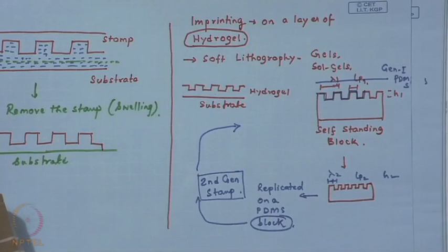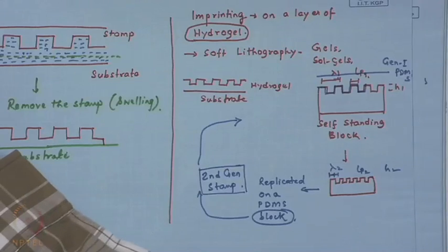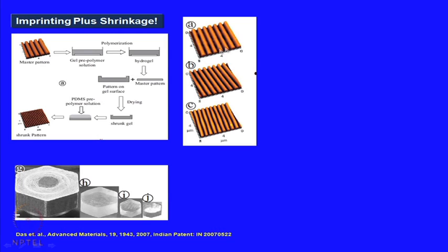So, you see here that starting off with a layer which is, let us say, a periodicity of 1.5 micron, in the second generation you achieve roughly 40% shrinkage. So, the periodicity has now dropped to about a micron. You can measure that. Here you have 8 micron and you almost have 8 stripes. Here you had roughly 6, and this now is the second generation stamp.